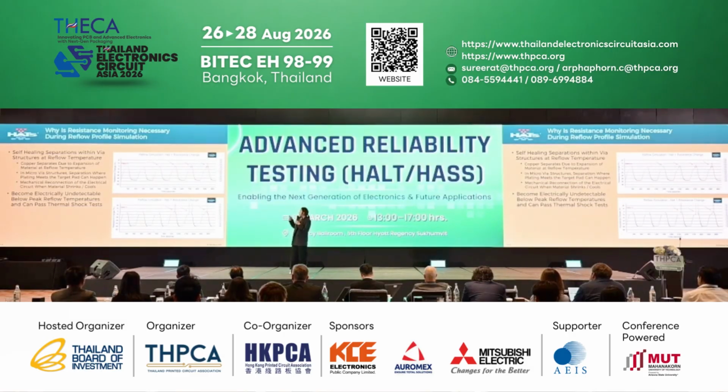As we can see, at room temperature or at the lower temperature of the reflow, the resistance change seems to be normal. But the difference is at the peak of the reflow. As we can see, the resistance change starts to fail, starts to show very obvious evidence.